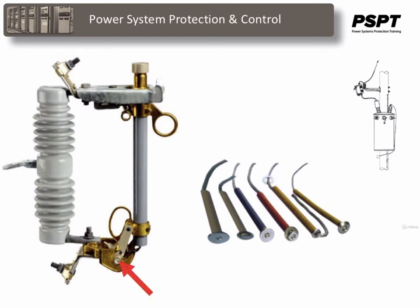Fuse fittings consist of a hinge and a jaw, and when the fuse blows, the fuse element releases the jaw, and the jaw falls open. You can tell that the fuse is blown because the fuse holder has swung down, and you can see it quite visibly from the roadside. The fuse holder usually consists of, as I said, a porcelain tube or some fiberglass tubing, which may be empty or contain solids or liquids to assist in the arc extinction.